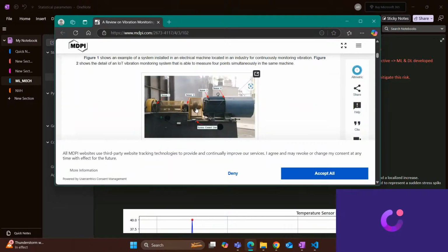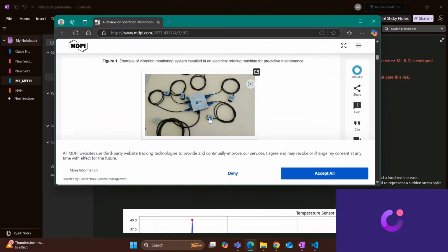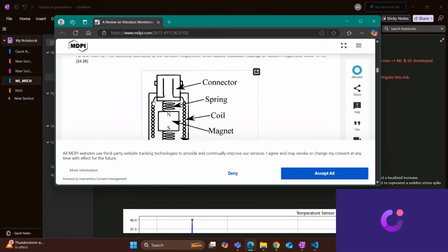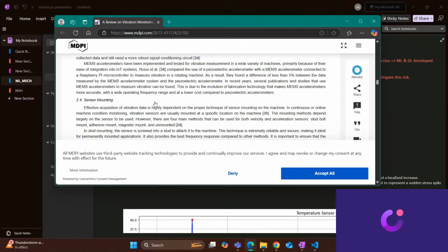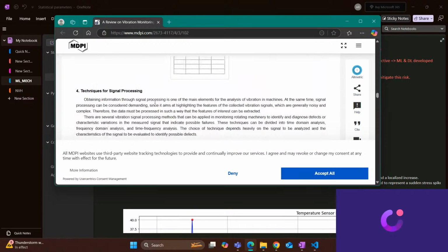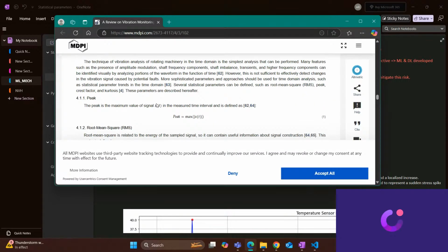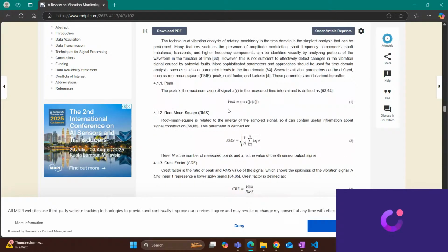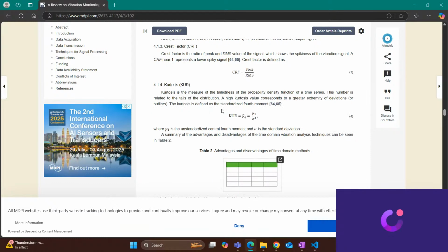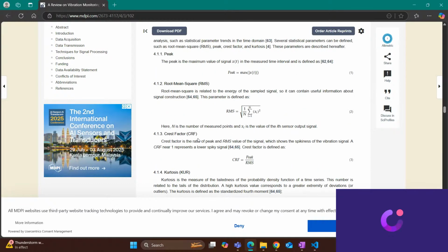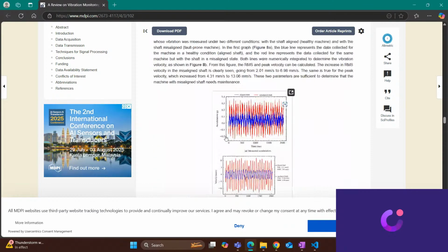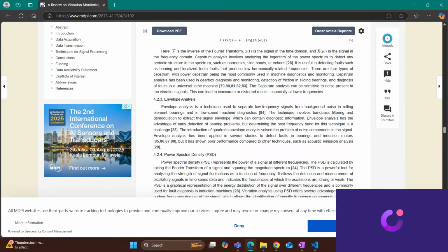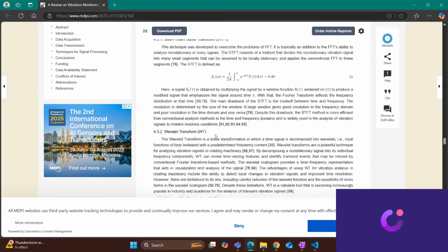So we have certain motor sensors measured here, right? And how do you do data acquisition, and how is AI useful for that? And what are the other measures compared, like statistical measures which we can use for vibration analysis, right? Where we can calculate the RMS values, the peak values, crest factor, kurtosis. So these will also help us to analyze the vibration data pattern, right? And even performing FFT or PSD also helps us to analyze the data.